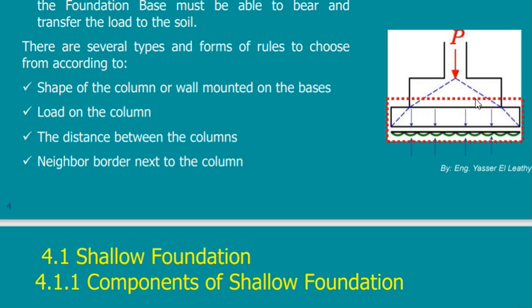This stress can be higher than the stress of the soil because it is not touching the soil, it is touching concrete. So if it is resting on concrete, then I can go with my stress higher than the stress of the soil. If this was the soil, then this area is not enough. I have to increase it. So by putting this concrete layer, I managed to increase the allowable stress, using the allowable stress of the concrete instead of the allowable stress of the soil.